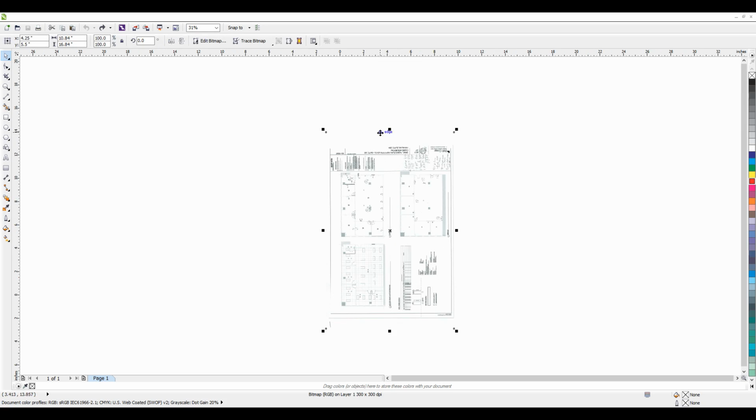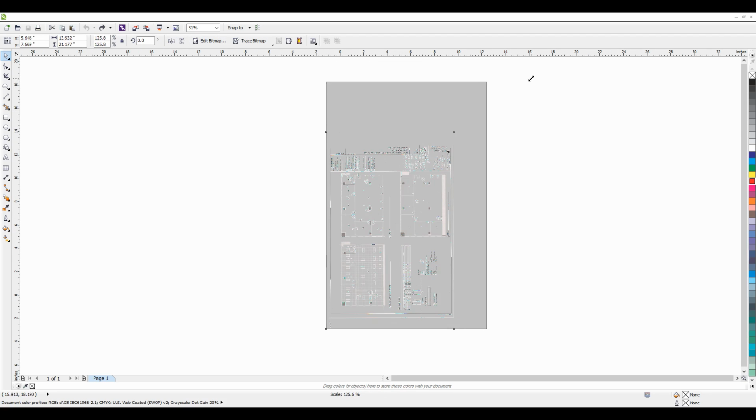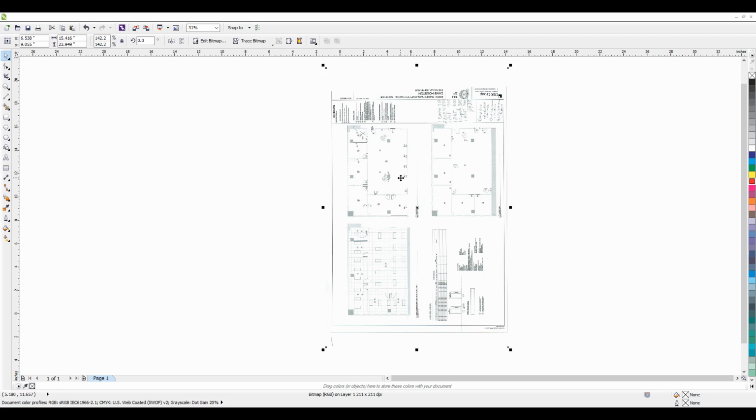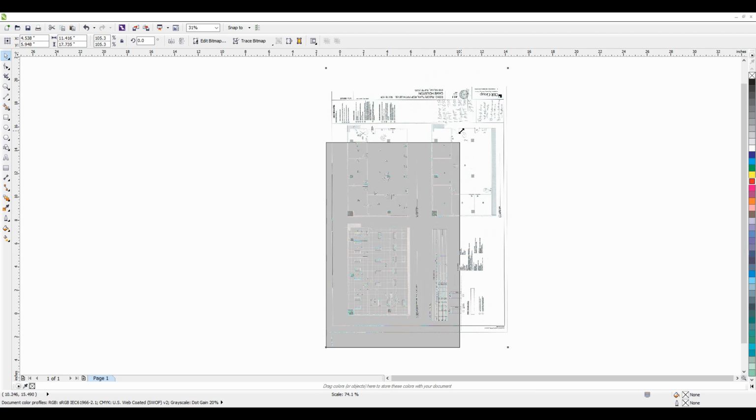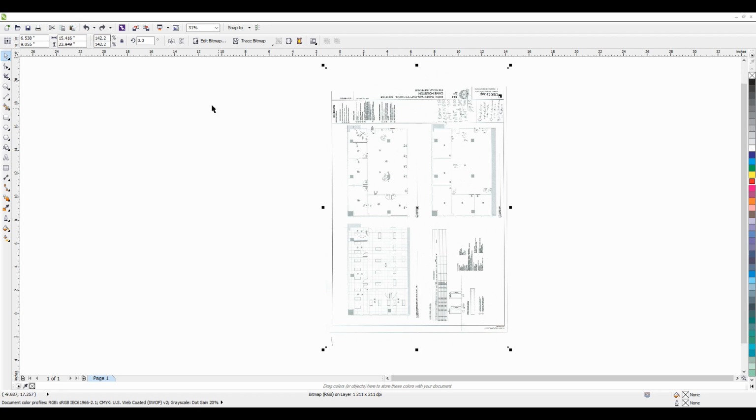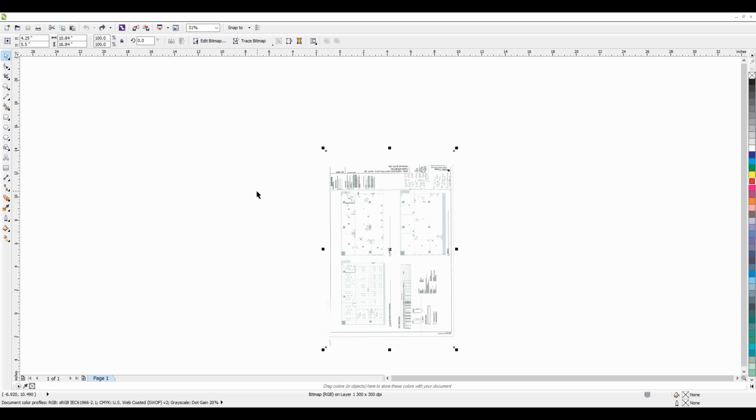Selecting it again to reselect it, like I was saying, dragging from the corner drags it proportionally. This is extremely important because if you don't do that, whenever you're scaling something, your whole scale is going to be off. Because presumably whatever you're starting with is that 1-to-1 scale, or at least proportionate to itself. You can use this to make it bigger or smaller, to increase or decrease the scale, but since we've done that, we've messed up the whole thing, so we're going to put it back to where it was. So all the way back.